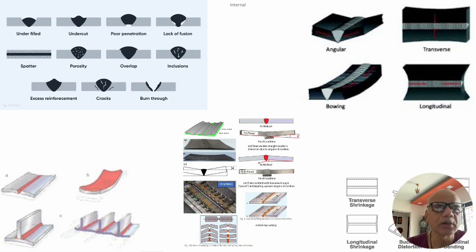The fourth defect, or the right hand top lack of fusion, is a defect which is sometimes difficult to catch with the naked eyes, because you see as if it is penetrated fully, so you assume that while it has penetrated, it has also fused on the side walls or the edge preparation which has been done onto the two plates or the two jobs which are getting joined. But actually it has penetrated, it has only come out of the groove, but it has not fused on the sides. Now surely if that happens, visually it is difficult to see it.